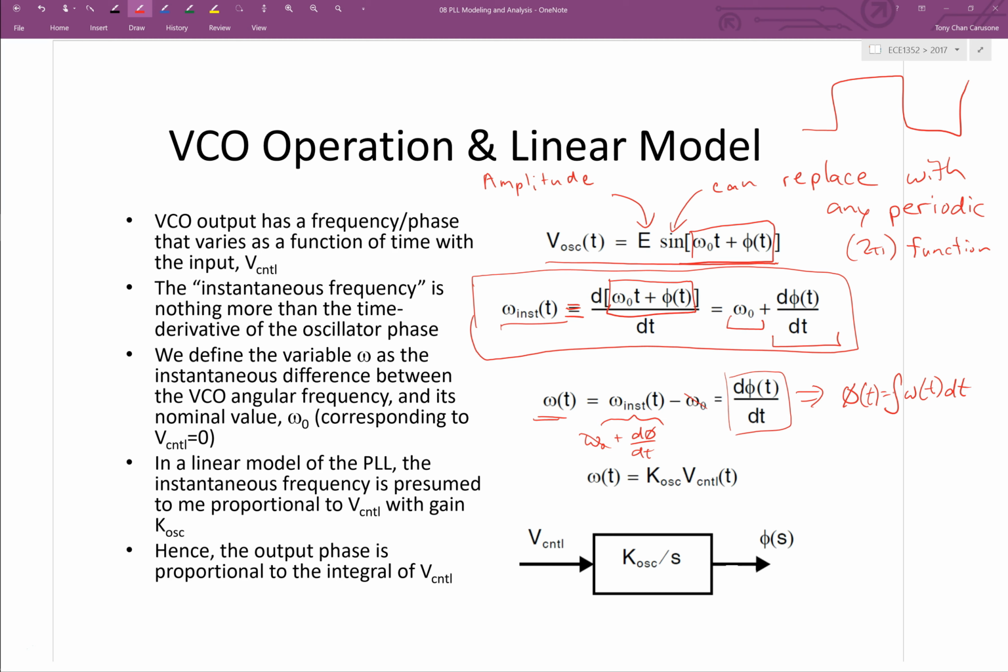So if we write that phase as a function of time, with respect to that red clock over here, one clock cycle it's here, the second one it's there, and every time this phase difference is getting a little bit bigger. The red is the nominal frequency that we're expecting, and the green is what we're actually getting out. So in that case, if we wanted to plot the phase of that green clock versus time, where red is the nominal frequency, we would get something like this. It's increasing with time, t.